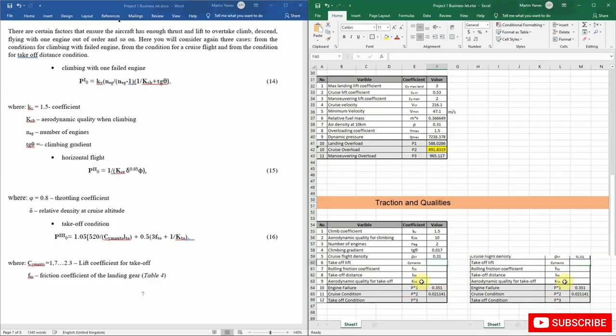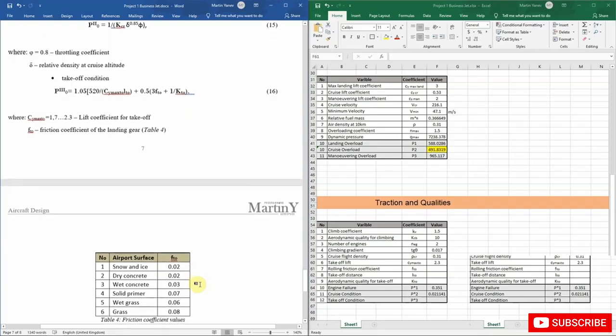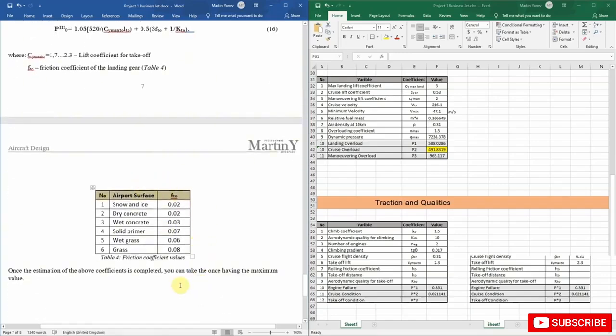So the takeoff lift, we will take the maximum to be equal to 2.3. Then we need to determine the friction coefficient on the landing gear when we take off. You can see the different friction coefficients here for the different types of surfaces. And obviously we need to take the worst one, which is on snow and ice. So we have it equal to 0.02. And this is the value I will be recording.